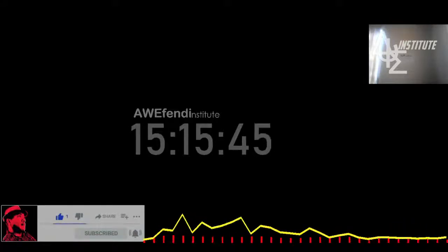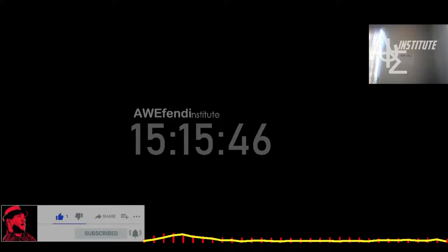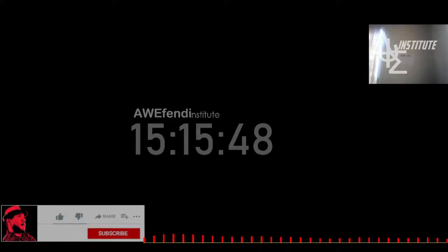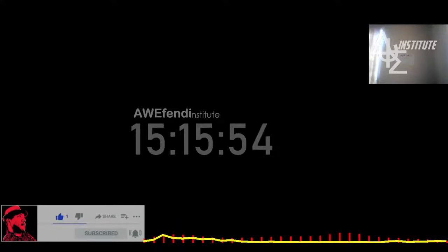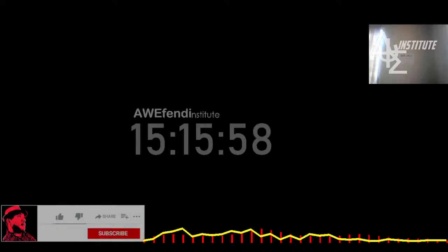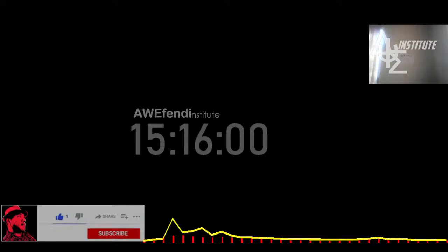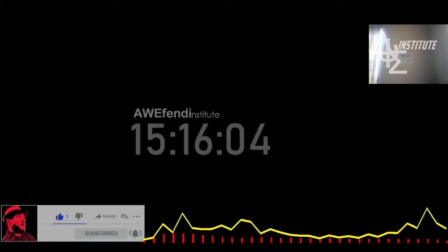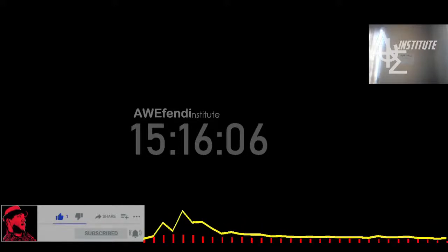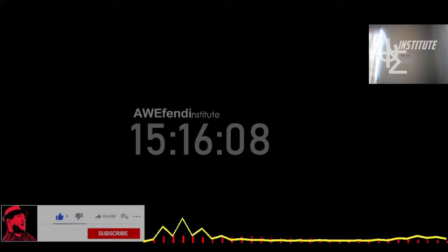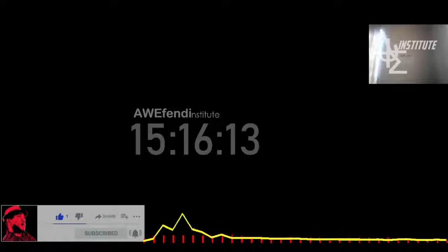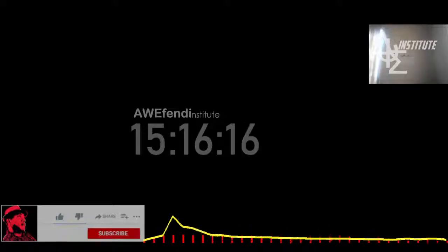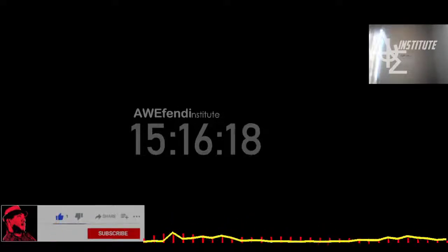So here we said it was 2 meters per second. Then we wanted 25 degrees Celsius. On the outlet, we wanted 0 Pascal, and for recirculation, we just leave it at 22 degrees Celsius. And that is pretty much our calculation set up. You can see here in the physics tree, we got our solid thermal boundary conditions, we have our fluid flow boundary conditions, we have our connections, so bonded contacts between the solids, and then our fluid-solid interfaces.